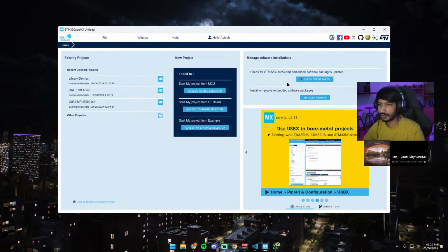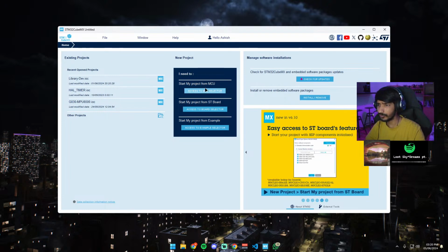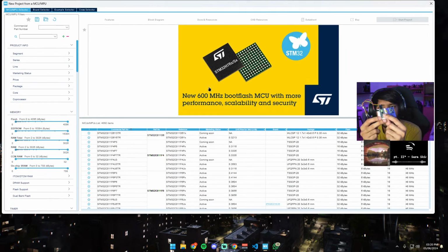All right, let's first. I have CubeMX over here. I have a small setup already made. I'm using an STM32 G030, a small microcontroller board which I have here for development, and I have an ST-Link connected over here through a wire with the interface of UART plus debug interface.